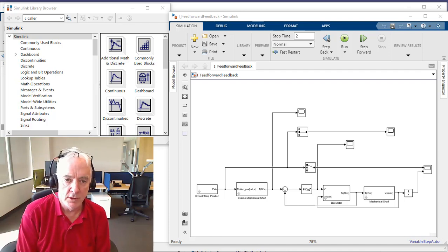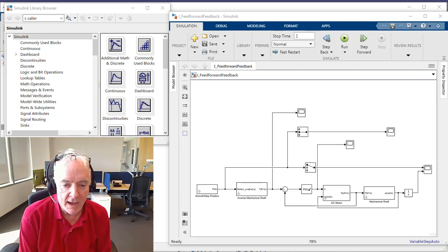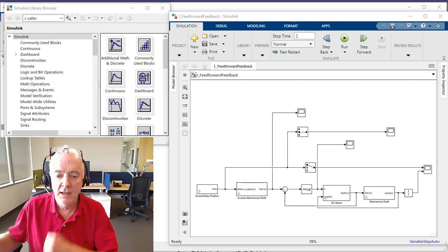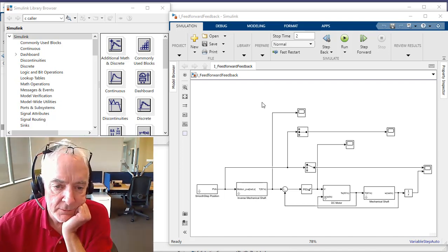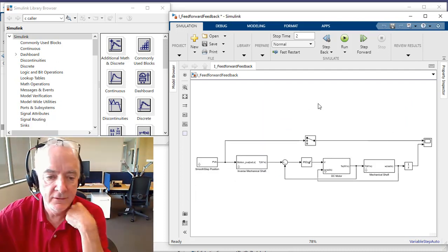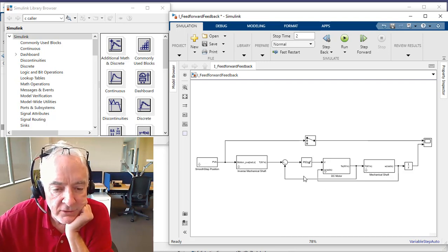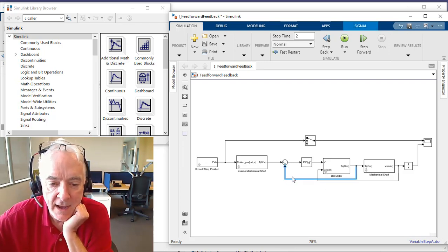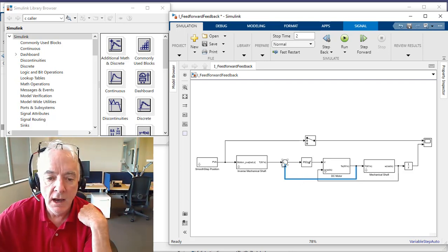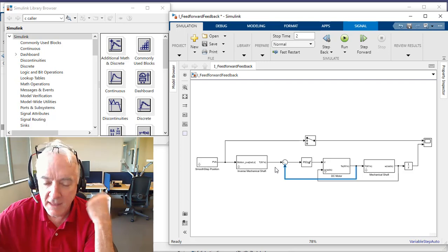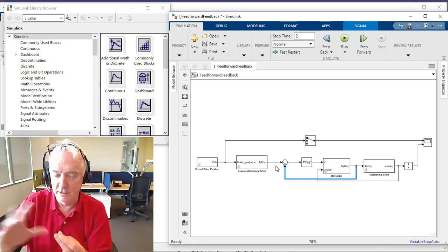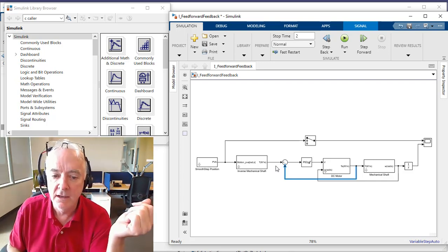So in this video, we're going to talk about feed forward and feedback and why it's pretty important to use both of them. Okay, and so let me delete some of the stuff from the last example. Essentially what we have here is feedback on electromagnetic torque, which we know is current times the torque constant, compared to our commanded torque. That's really an electrical thing again, because torque and current are scaled essentially, but represent the same thing, right?